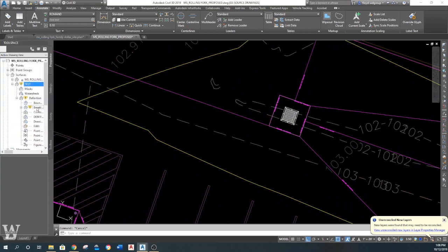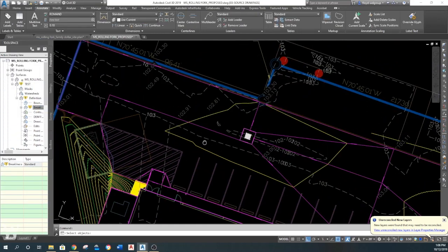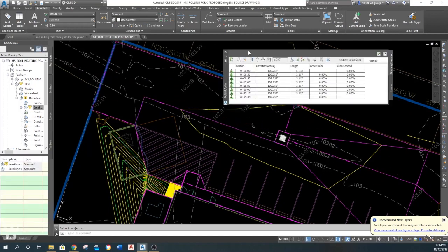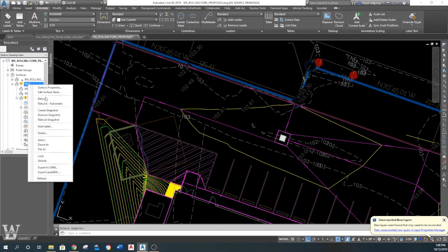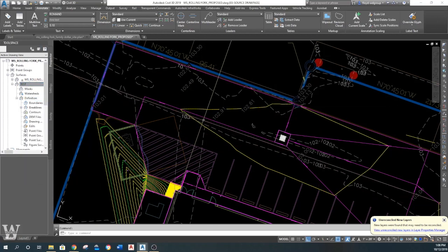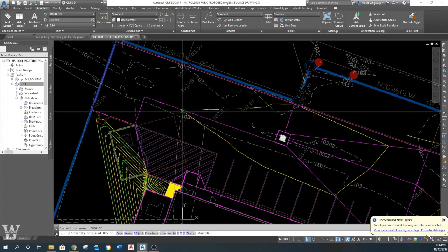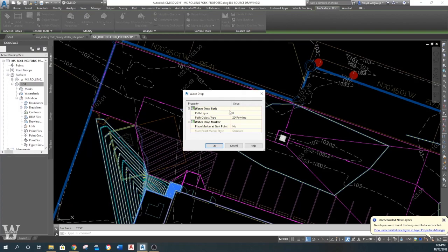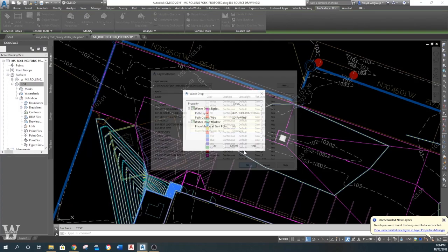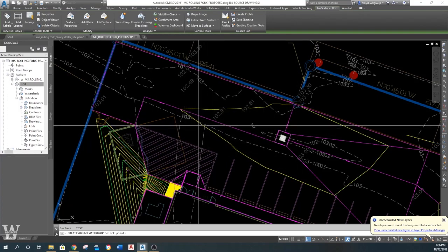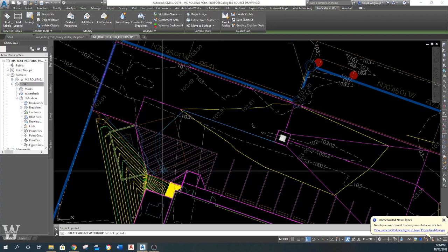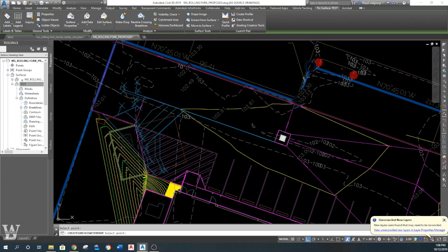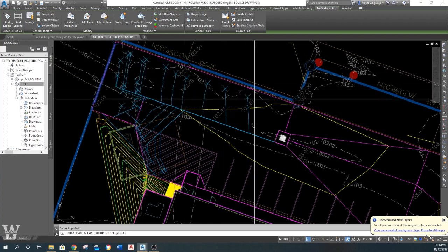And go back here, go to brake lines, add brake lines, pick these up, those are still okay, close that, regenerate my drawing, rebuild my drawing, see it move that line over just a little bit, change my UCS back, turn my snaps off, click on here, water drop, pick my path, elevate, layer, yes, okay, and it's going to go like that.